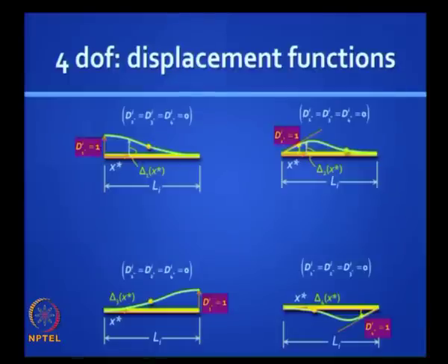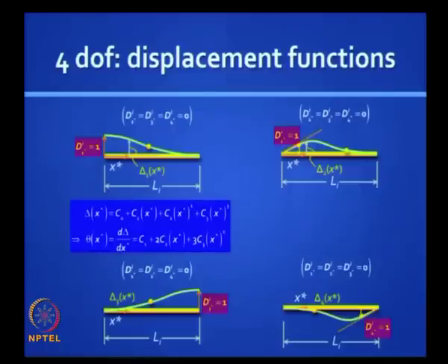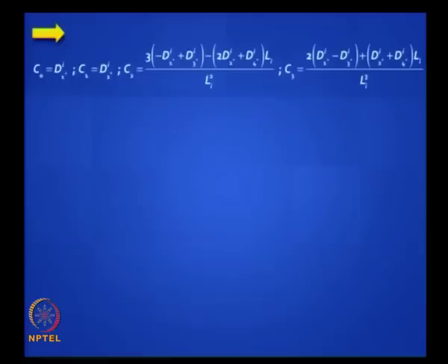From this, can you pull out the definitions of stiffness coefficient? Well, you can, but first you write down an expression for deflection. You have 4 boundary conditions, write down an expression for slope, apply the boundary conditions, and you can actually get equations for these deflected shapes. I have shown you 4 deflected shapes and I am making a tall claim. The claim is any arbitrary deflection in that beam can be obtained as a weighted average of these 4 shapes, right. Let us prove it.